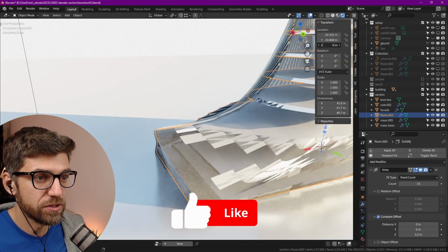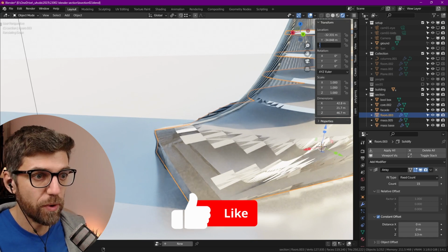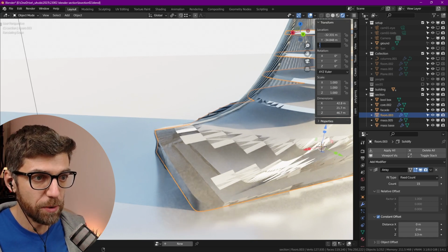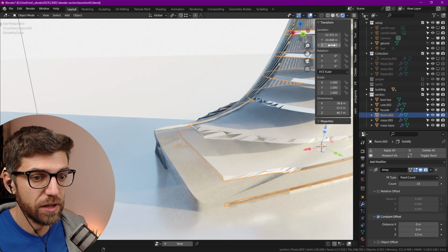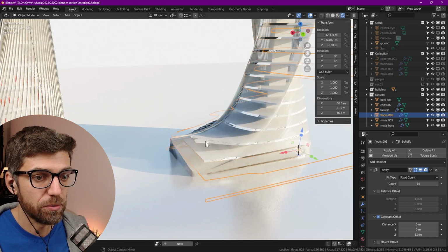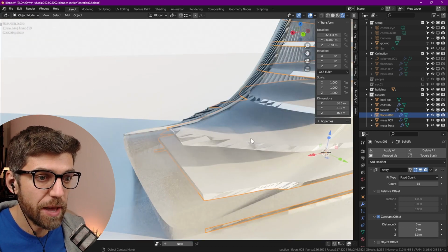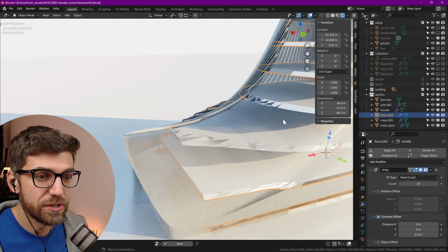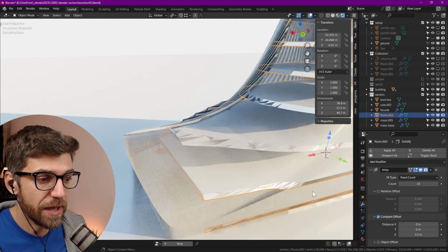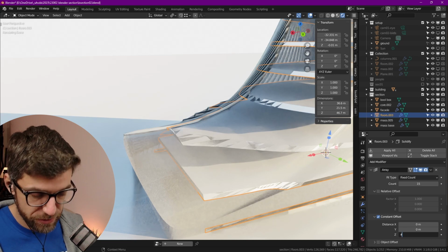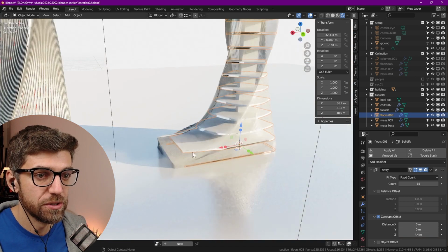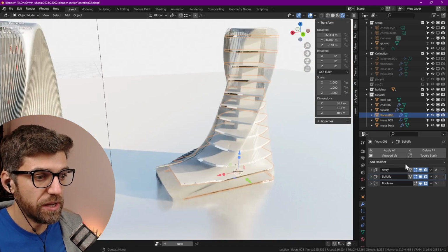When that occurs, the best thing to do is just to try to move the object up or down by a small amount. And usually those artifacts go away. In this case, it's a precise overlap between the faces of the floors and the face of our massing. So I'm going to put this back to 4.4 meters, contract all these booleans, and now let's create another